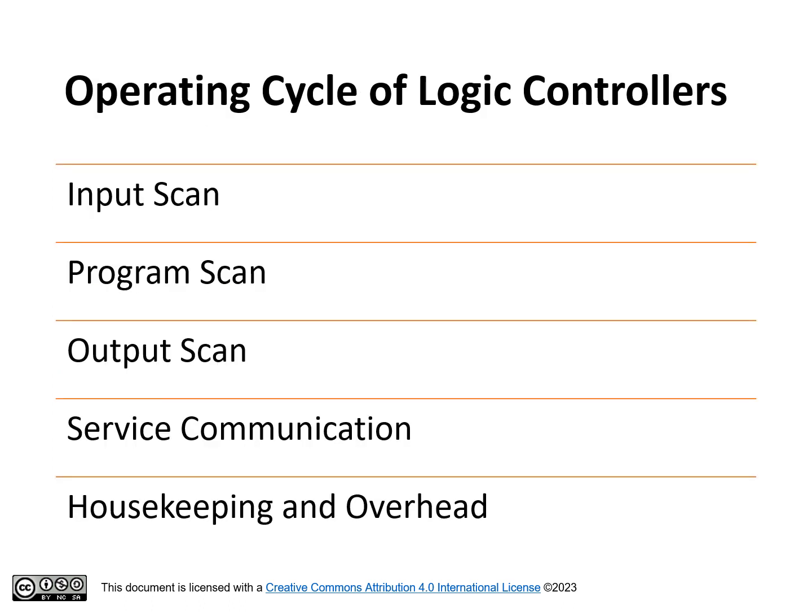After the ladder logic program is loaded into the controller, placing the controller in the run mode initiates an operating cycle. The operating cycle consists of the following series of operations performed sequentially and repeatedly unless altered by the presence of subroutines in the ladder logic program and system interrupts.